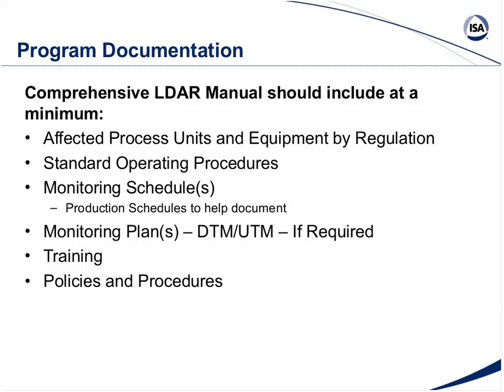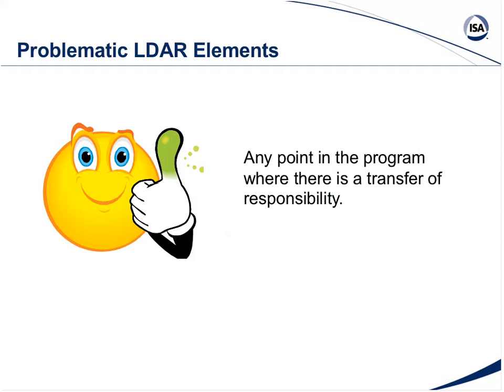Usually it's prior to a turnaround where you're getting scaffolding built, and so now you have the scaffolding up there. And then it becomes a question of how do I track when my scaffolding comes up so that component is safe to monitor and I can go out and do it. So those are some of those little nuances that people are starting to look at over and over again: is it safe to monitor? And how do you, as the LDAR coordinator, know that if you're inside the office and then all of a sudden you walk out and there's a whole bunch of new scaffolding that's been put out in your plant? You want to keep your training documentation, what kind of training is there, and whatever your policies and procedures are.